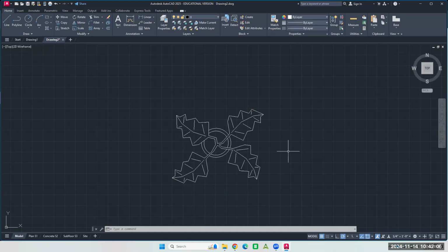Yep. So it's like when you're placing hatching. We haven't done that yet, I don't think. Hatching goes in as a block, but if you explode it, all of those lines become individual lines, and that's stored in the registry. So you can undo and undo back. Once you place it and explode it, it's in there, unless you don't save. Because then you have the opportunity to undo it, that puts it back into a block, and then you could save it as a single block. So just be careful with it.